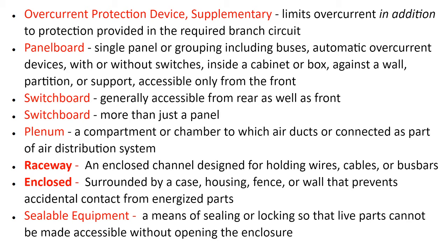And so just some more basic words you need to know in this industry. There's supplementary overcurrent protection, which may not be the main overcurrent protection device. So you might have a solar circuit that's landed on a breaker, and then you might have module level regulators. Those module level regulators would be supplementary devices that are in addition to the main breaker.